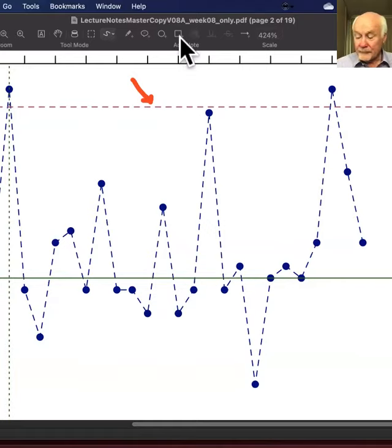So in statistical process control, we normally use some sort of threshold like that. It's more common actually to set these outlier lines a little bit higher, so that it's maybe 3 in 1,000. But I think for a lot of practical purposes, just using the box plot upper fence makes sense, and it means you don't have to remember another calculation.